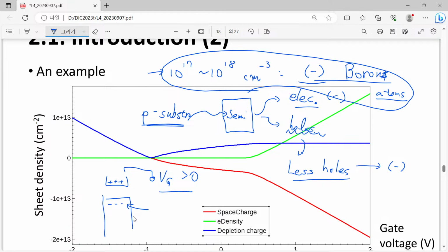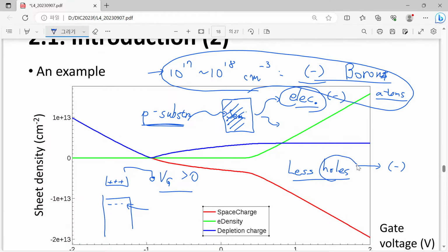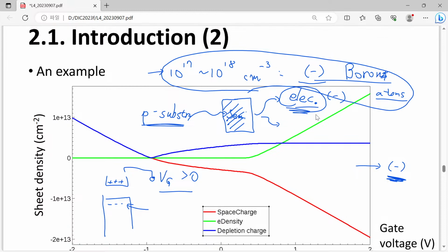And the semiconductor part should provide negative charges, but fortunately this semiconductor can have two different mechanisms to provide them. First of all, previously I had holes, but I will just remove my holes. Then I can provide the required negative charges. Only after some bias voltage is the second mechanism activated, and this directly provides your electrons.